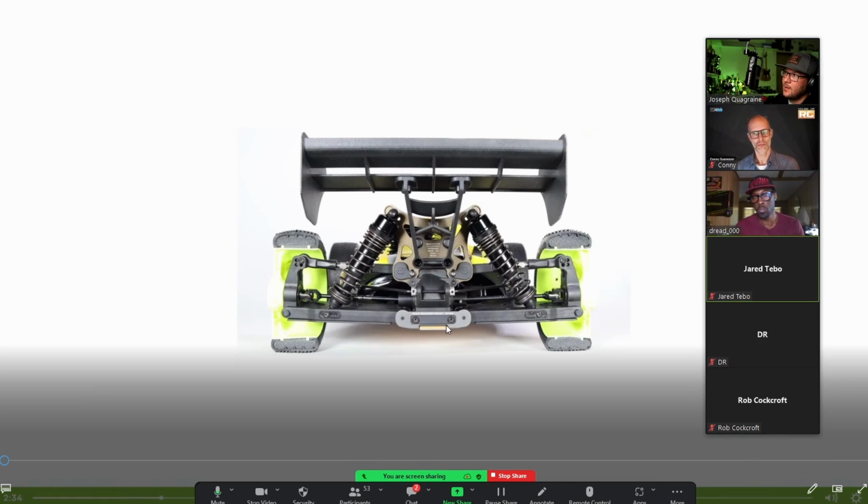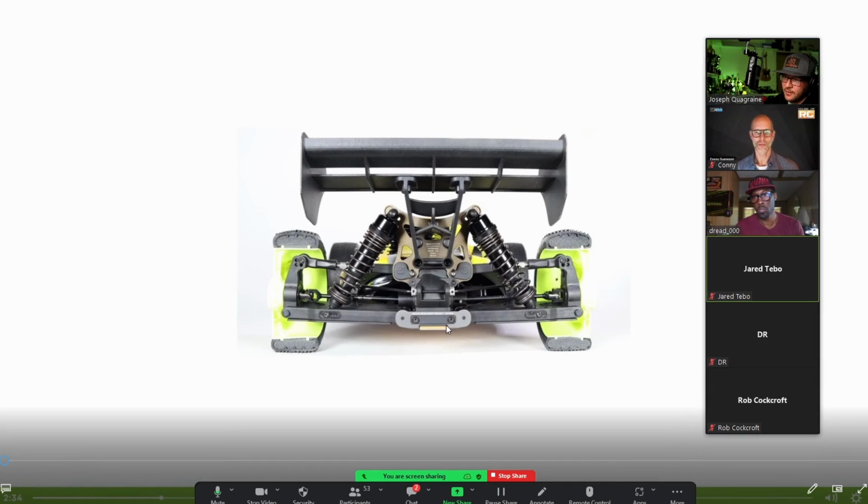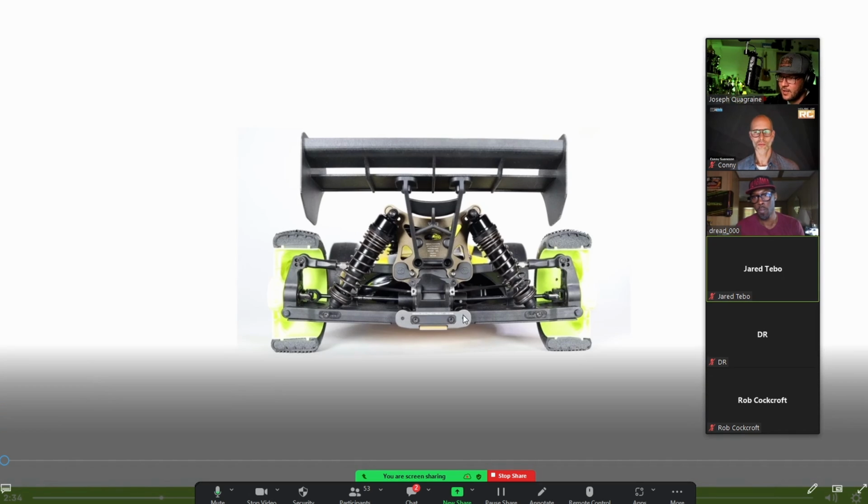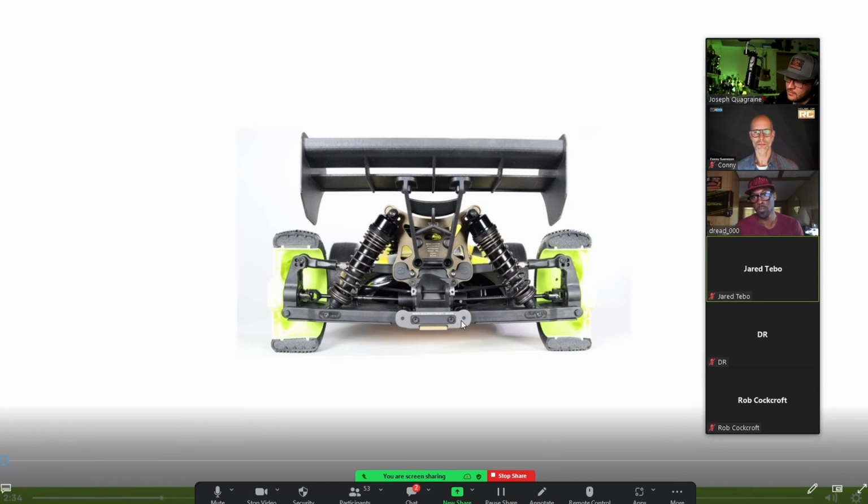And it has to do with the traction level of the track, the speed of the track, the layout of the track. If there's a lot of high speed corners where you're really pushing the car, you can get in trouble if the car squats too far. Working range, remember, you want to keep the car within the working range. So it could be hard to drive because the arm is low, allowing the car to squat too far in some sections. So then it can be easier to raise the arm a bit, gain some support, keep the car within the working range. You're good to go.